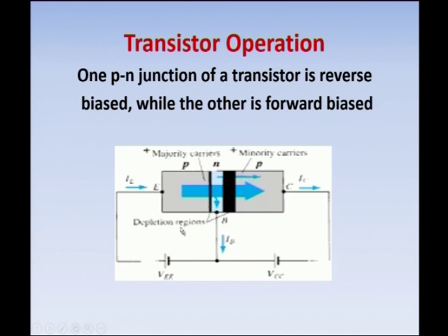How the transistor is operating, and how the current is maximum at the emitter terminal and at the collector terminal. For the transistor to be operated in the active region, we will see it later. Now, for the transistor to work in a proper condition, you have to give the input junction forward bias and the output junction reverse bias.